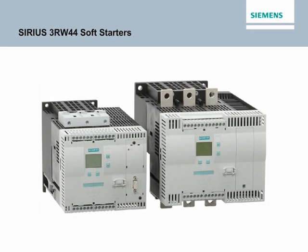An RS-232 serial interface is provided to communicate with the soft starter ES software for easy configuration or a display for external operation and monitoring. Additional features include, but are not limited to, motor overload protection, thermistor motor protection, selectable current limiting, multiple starting and stopping braking modes, intrinsic device protection for thyristors, and optional Profibus DP communication.